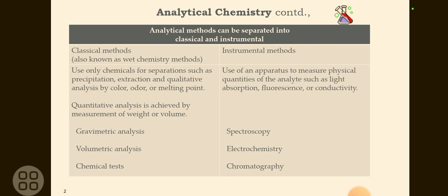For that we have some guidelines like the APIC guidelines. According to the APIC guidelines, for the KSM or the intermediate, we have to show the cleaning down to 100 ppm, based on the calculations. So once we clean that vessel, the cleaning solvent should contain not more than 100 ppm. By that we will ensure the vessel is completely cleaned. For that we first prepare a standard solution of 100 ppm and run it in the UV. We will get a UV maxima with a specific absorbance at a particular nanometer.